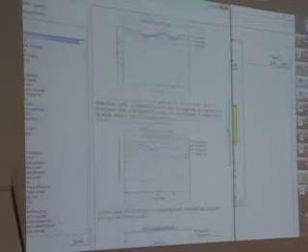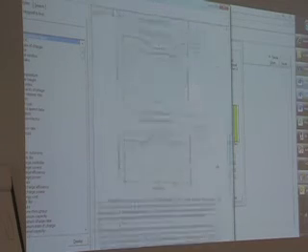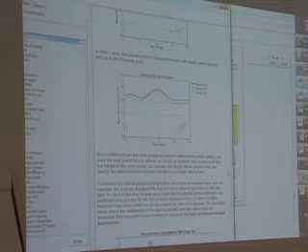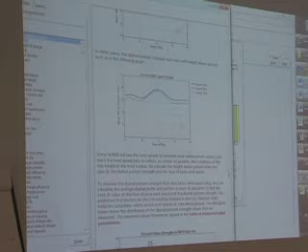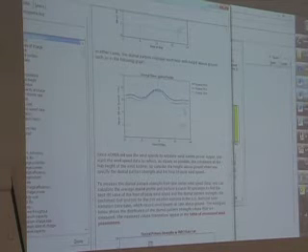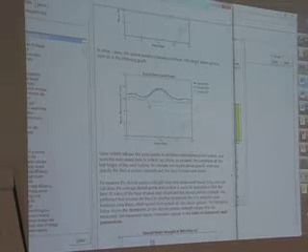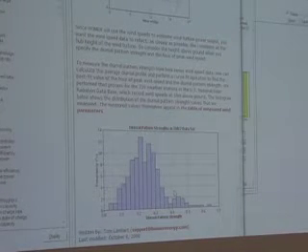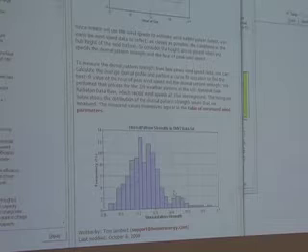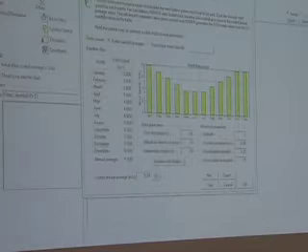And just to show you for the other parameters. Diurnal pattern strength is interesting because as you go higher, it obviously gets more stable, but the diurnal pattern actually shifts. So you should look at the help file. Anyway, here's the sort of range of numbers. There's a few places out here. These are probably places with sea breezes, which are a really pronounced diurnal pattern, where the sun comes up, heats the ground, creates an afternoon wind.